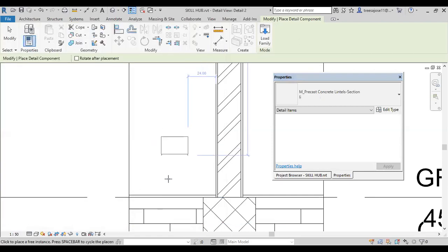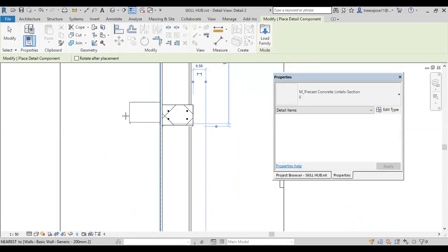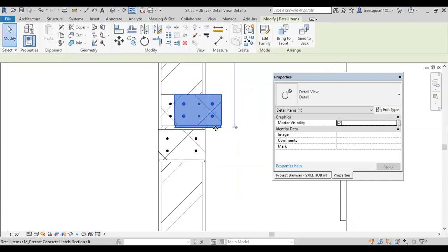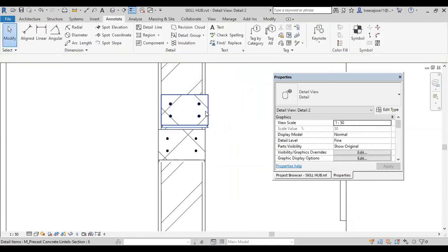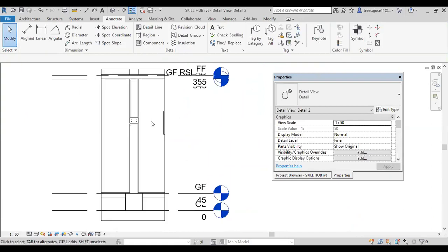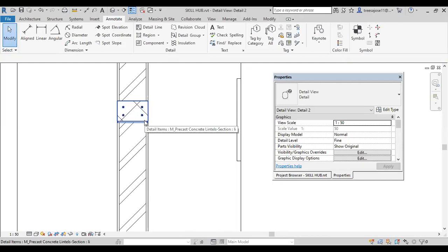Then you can place it wherever you need, because whenever you create a level, then you place it and it is placed automatically in the corresponding correct position. Automatically, that will be added in that position. I think you better create a level, then align it. That is better. Automatically that will appear in that option.